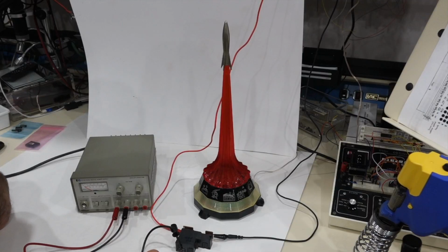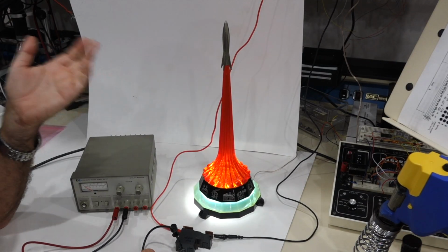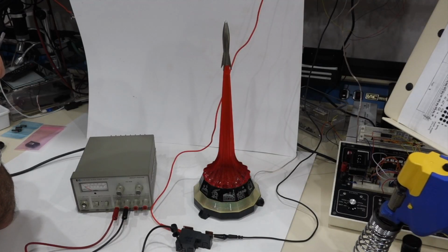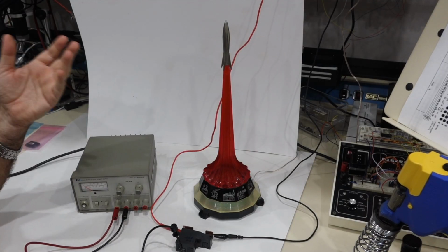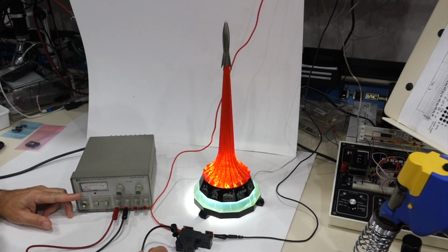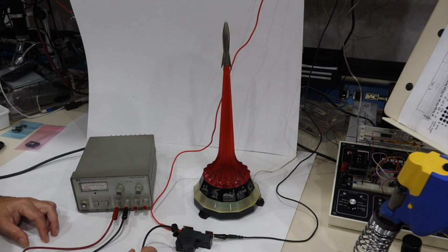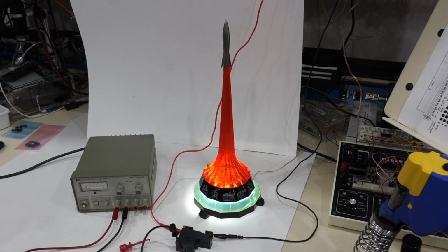It's included in your mechanical relay, right? If you don't have to refresh anything, it stays there once you have put it in the right condition. And then it solves the power consumption problem, because if you look at here, it only consumes power when you switch it. Then once it's over, it's done, right? So 3 problems solved at once. The downside is, of course, that you need a gajillion billion relays and you need to make them flight worthy, which is not that easy, but they managed to do it.